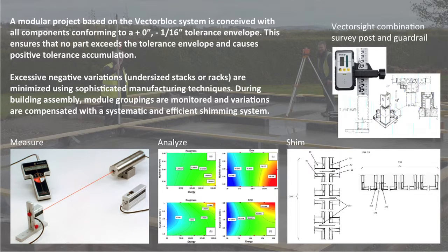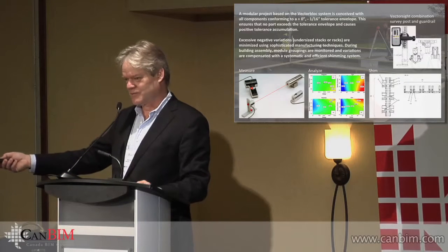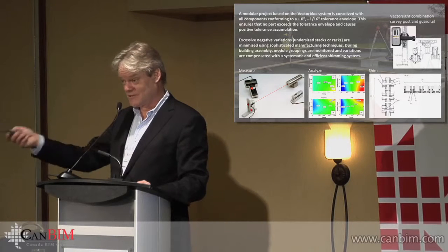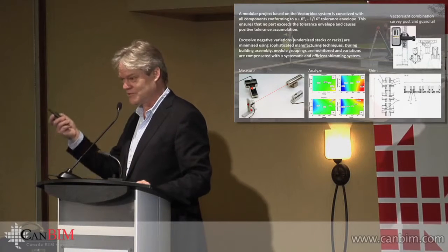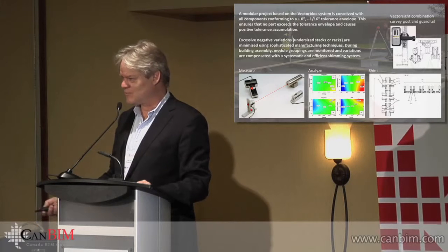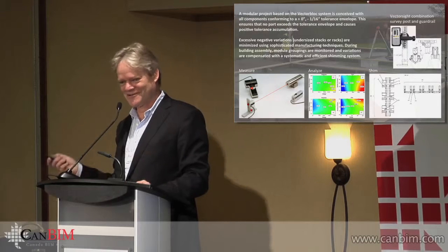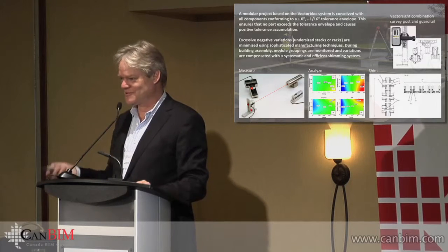And then in the bottom right, it shows you how to place shims in order to deal with that. So let's say that after 5 floors, you've got one corner of the building that's dropping, a 16th low, and I truthfully believe that we will be able to hold that sort of tolerance. Then you can slip in one piece of 16 gauge sheet metal as big as the top of the connector and keep going. So that becomes the process.